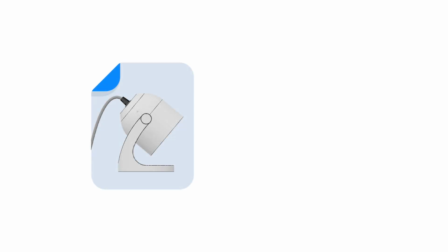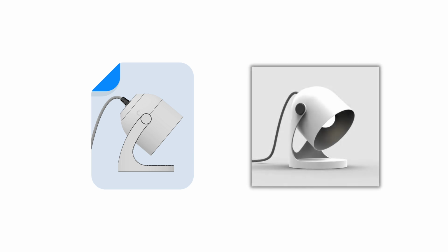And to get your mechanical engineer going with this 3D model, you will need to send them the 3D model that your designer did, the one that has the exterior major dimensions, which the mechanical engineer will be using as a reference. And then apart from that, you will hand the mechanical engineer the rendered images that you have been using for concept validation.